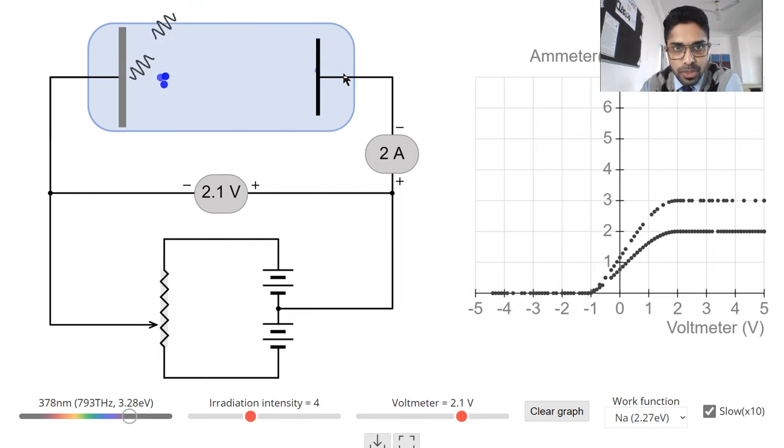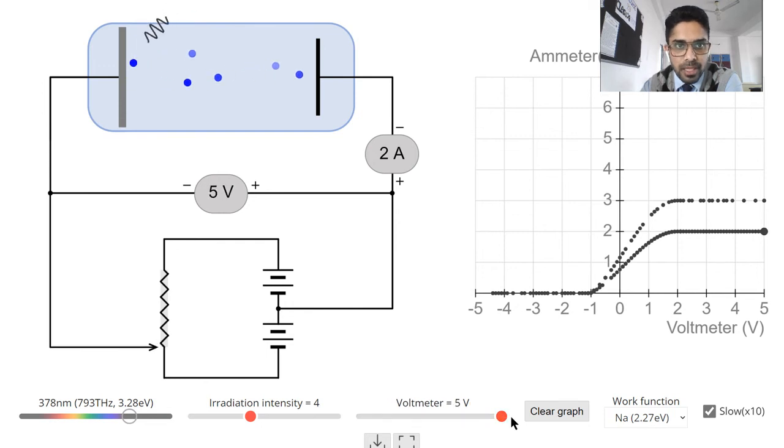So that's why you see after that, it doesn't matter whatever be the highest value of the voltmeter's reading, say up to 5 volts, there is no change in current. Why? What is current? Charge flowing per unit time. Charge per second. So maximum we are getting 10 electrons per second, right? Even if you are making it more positive, it cannot attract any extra electrons. Are you getting the point? If the emitter is emitting 10 electrons per second, the collector will receive a maximum of 10 electrons per second only. Your supplier is providing 10 electrons per second, you will only get 10, never more than that.